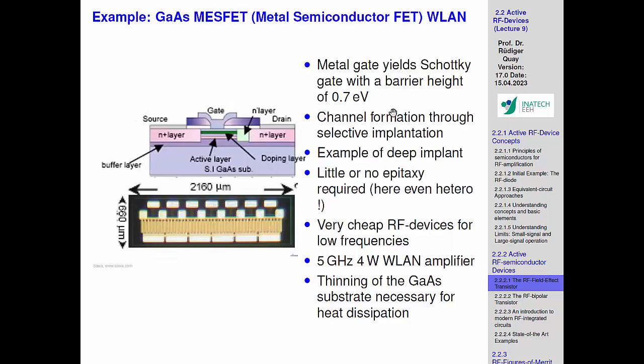And as I said earlier, the people didn't do that in the beginning. They just looked at other materials and wanted to do things simple. So they were just putting a simple gate, now back in gallium arsenide, on a substrate. This is now the MESFET. So you have, as I said, some doping profiles here and an implant layer in the channel region. So this classical MESFET, Schottky gate, yeah.